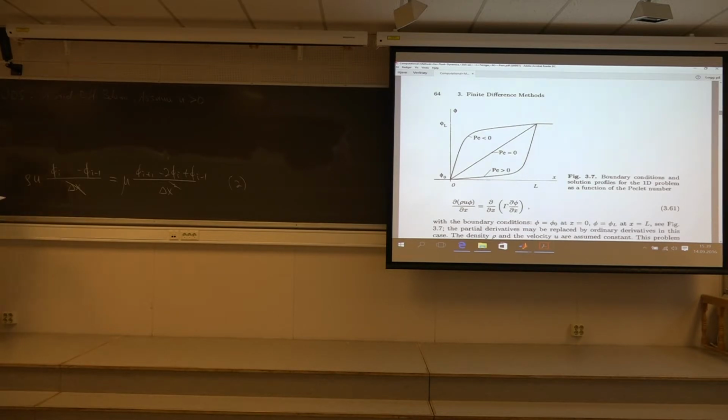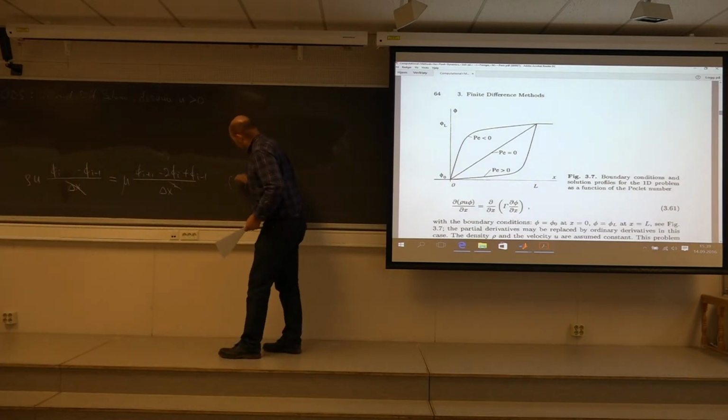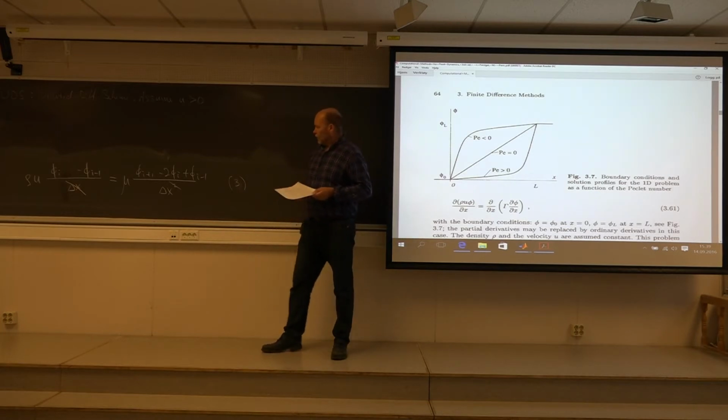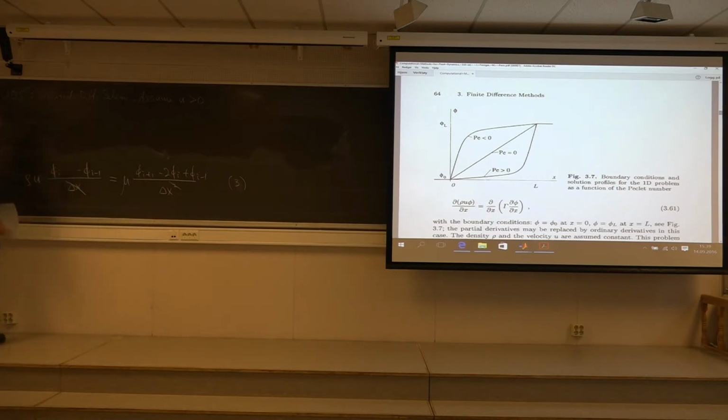So then you will have your discretization scheme very close to the one with the central scheme, but here it's an upwind differencing. It's first order accurate only, but this then, according to the theory, should stabilize the code. Now let's see what happens.